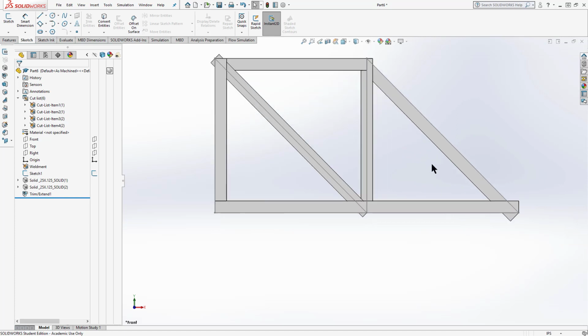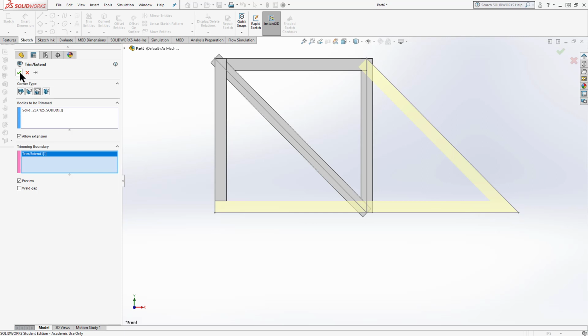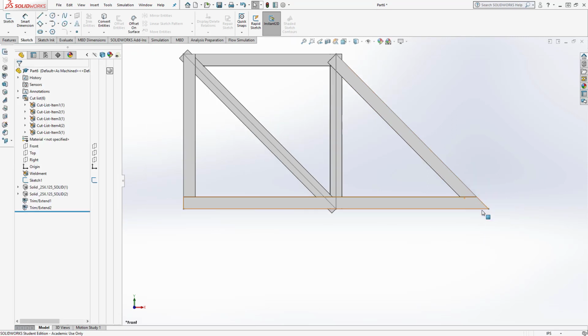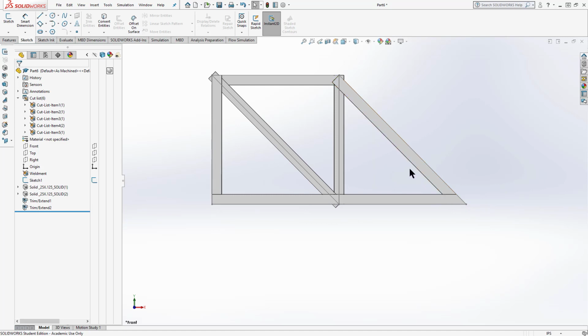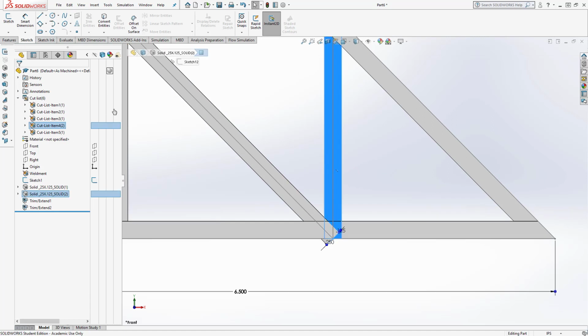Let's do a similar item on this end. So another trim of a butt joint, the exact same butt joint, and I'm going to trim my angle and that bottom. Now you'll see that's a stronger joint than my miter for the way the forces are going to go into this element. So that was easy. Let's do my last one here, this one.